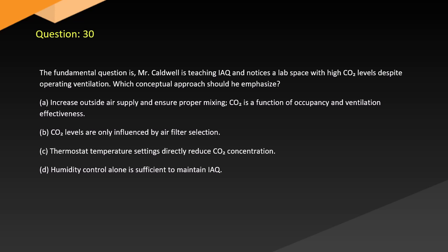Question 30. Mr. Caldwell is teaching HVAC and notices a lab space with high CO2 levels despite operating ventilation. Which conceptual approach should he emphasize? A. Increase outside air supply and ensure proper mixing. CO2 is a function of occupancy and ventilation effectiveness. B. CO2 levels are only influenced by air filter selection. C. Thermostat temperature settings directly reduce CO2 concentration. D. Humidity control alone is sufficient to maintain indoor air quality.